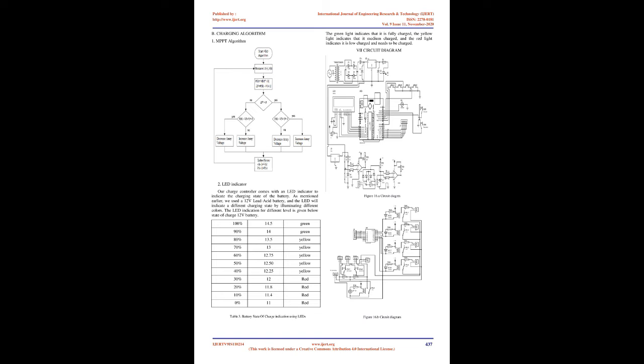The figure shows how the IV curves vary with the intensity of light falling on the panel and also on the temperature of the cell. It is also called a hill climbing technique. To the left of the peak in the PV curve, the operating voltage is increased, and to the right side, the voltage is decreased. This results in the operating point oscillating about the peak power point.